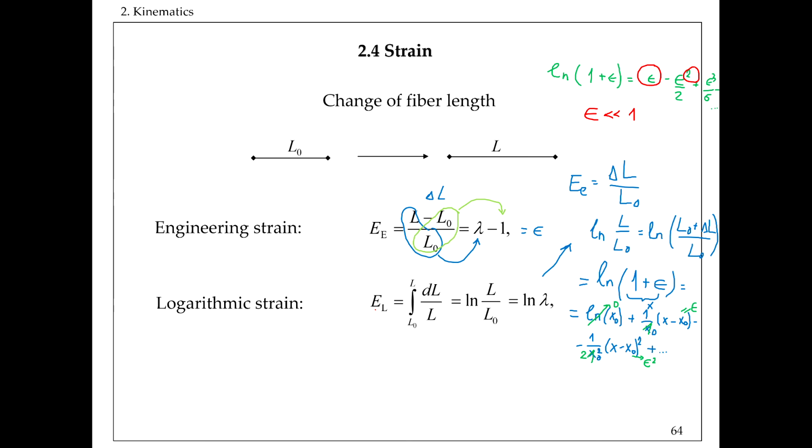And so going back with that, again, this is our choice how we define the strain. We can define it in different ways, but we just need to remember that if we want to deal with large deformation and be more accurate about it, then we probably want to keep these higher order terms still in play. Otherwise, we'll not capture what is sometimes called geometrical non-linearities.